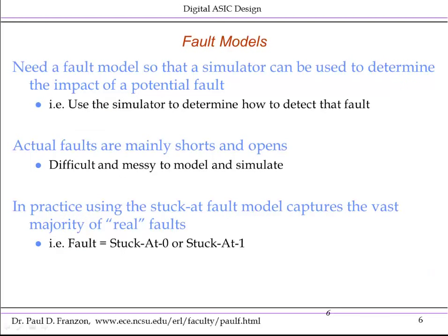So to get all this rolling, you need what is called a fault model. That is a model for the fault that can be simulated in the simulator, so that you can determine the impact of a potential fault. There's a model for the fault that can relate itself to the logic of the chip. Actual faults are mainly shorts and opens, and transistors and wires that are out of spec.